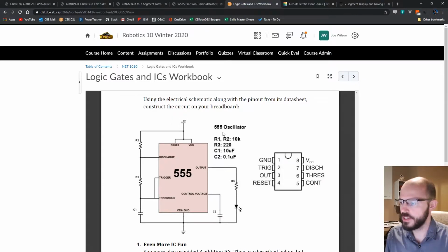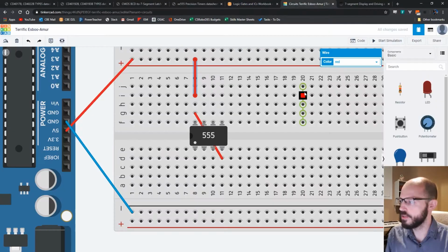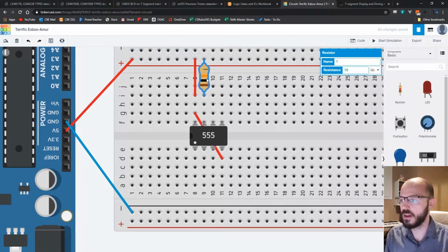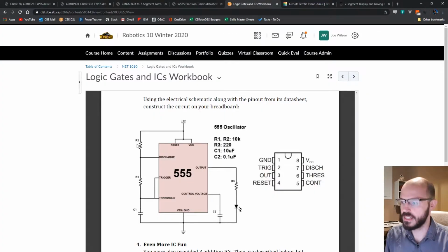And what kind of resistor? Well, I've labeled it here as a 10K ohm resistor. So let's go find that in Tinkercad. We'll grab a resistor from pin 7, that's this one, up to 5 volts. I'll just make this 10K. Once again, yours are different because yours use the 4-band color code system and these are the 3-band color code system. So your 10K ohm resistors are the one with the single red stripe in the second position in. And that's going from pin 7 to 5 volts, and that makes this connection here.